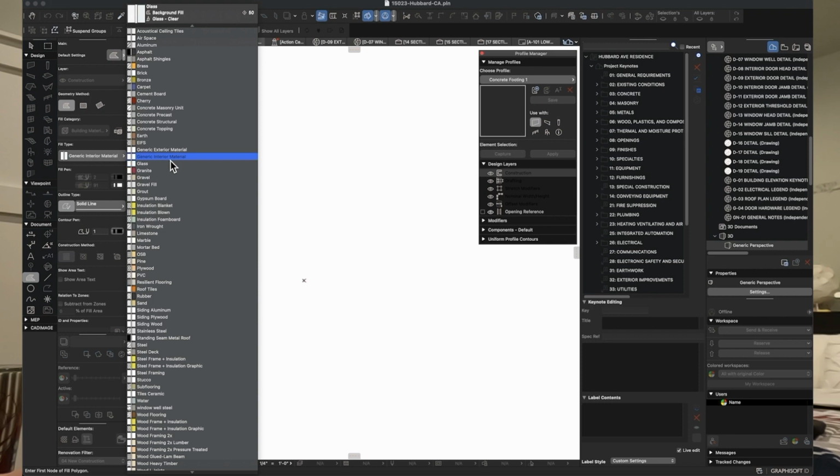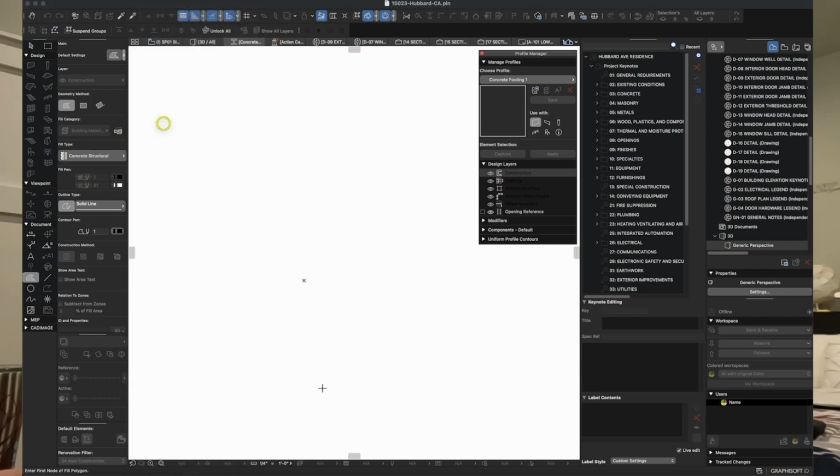So imagine you're taking a section cut through the building, and whatever that section cut is, that filled area gets extruded out. It becomes linear across the face of the building. So in this case, let's start with a concrete. We're going to go concrete structural. And for my origin point, I'm going to make that the profile line of the complex profile.